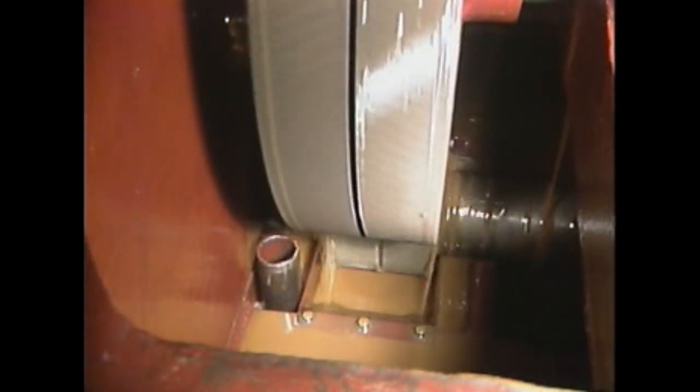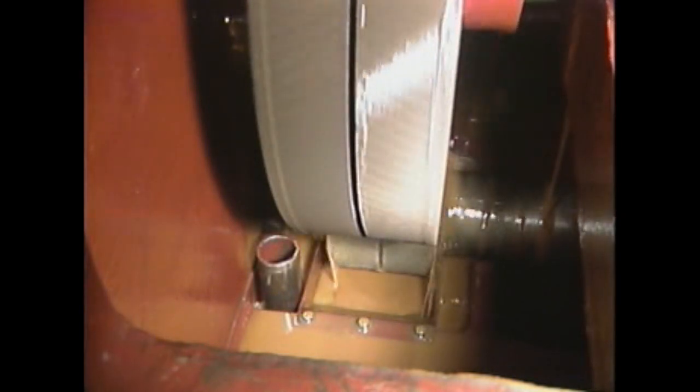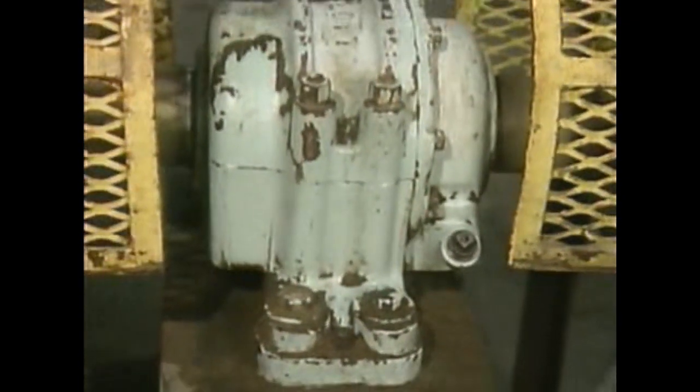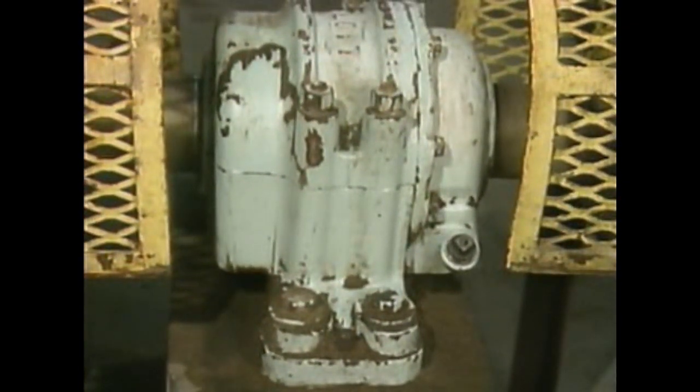Speed is also a factor in lubricant selection because there's a higher rate of wear at high speeds than at low speeds. Generally, low viscosity oils provide lower friction and better heat transfer at high operating speeds than high viscosity oils do. In short, low viscosity lubricants are more suitable for components such as certain bearings where the loads are light, the speeds are high, and the system is fully enclosed. High viscosity lubricants are more suitable for components such as open gears where the speeds are low, the loads are high, and the system is not enclosed.